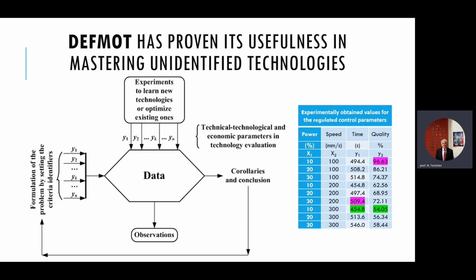The formulated problem falls under the nonlinear bicriterial optimization, defined by two nonlinear regression models describing the time and quality criteria. The problem is also defined as two-dimensional based on the two controlling technological factors. To define the problem, it is necessary to derive the models from the table of combinations, one for the time of image formation and the second for the quality of the image. Both models are a function of the control input parameters, namely the normalized power and beam speed at marking.